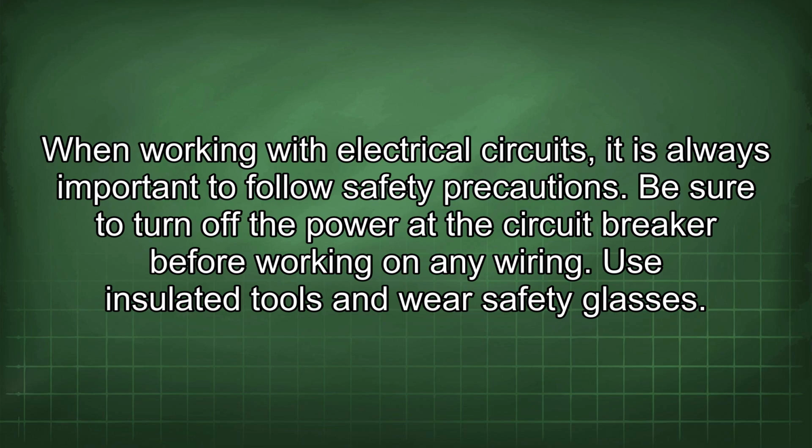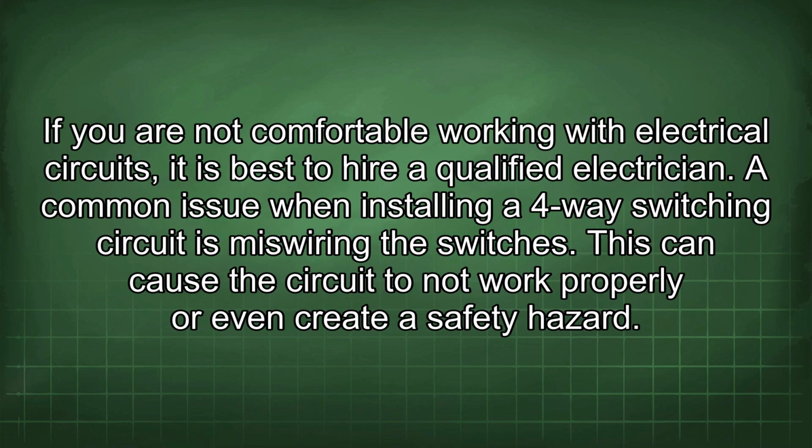When working with electrical circuits, it is always important to follow safety precautions. Be sure to turn off the power at the circuit breaker before working on any wiring. Use insulated tools and wear safety glasses. If you are not comfortable working with electrical circuits, it is best to hire a qualified electrician.